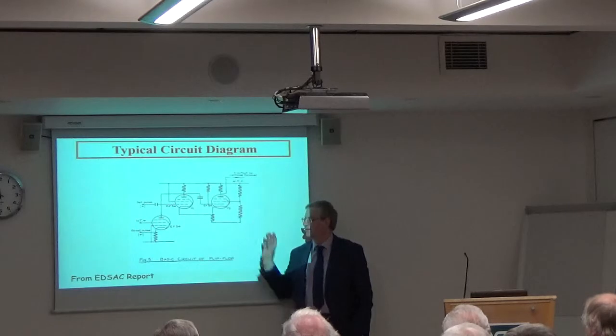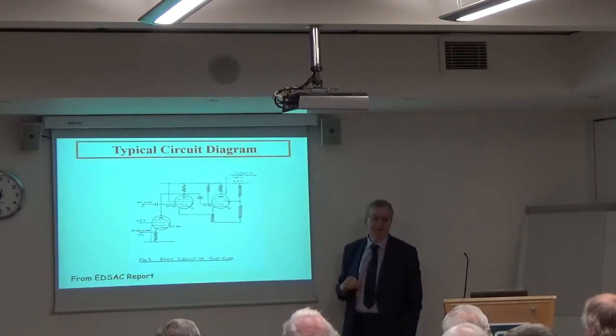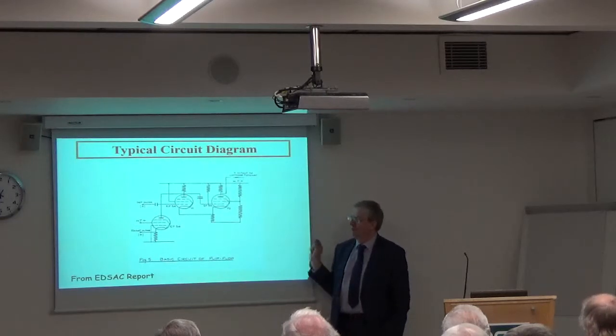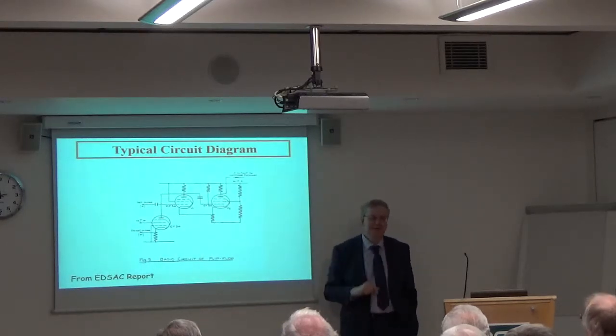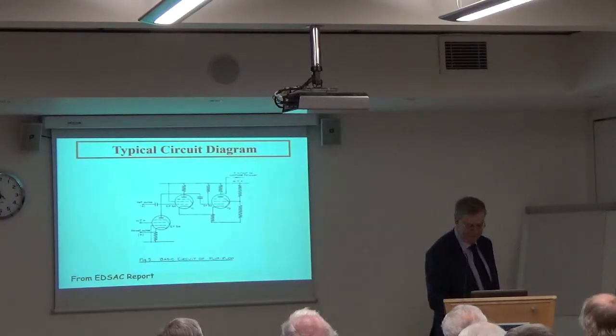And there is no set of values that we found to make that behave. We've had to switch to a later circuit we found on some of the diagrams that is a passive bistable. Having done that, when we went back through the photographs, we convinced ourselves, reasonably convincingly, I think, that there was a bistable even as early as 1951. We spent a year having the same experience that pioneers probably did, wondering why this monostable circuit wouldn't work in that one situation.